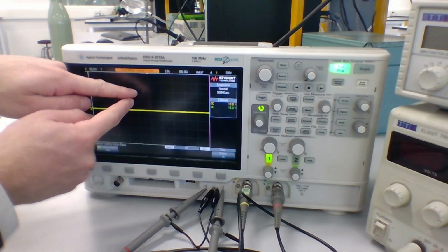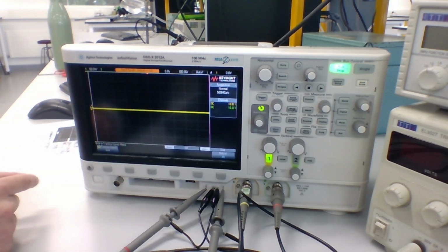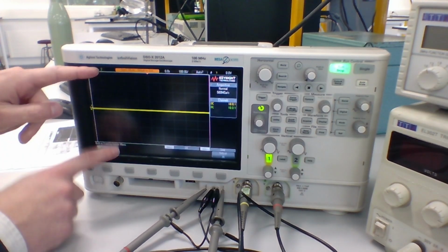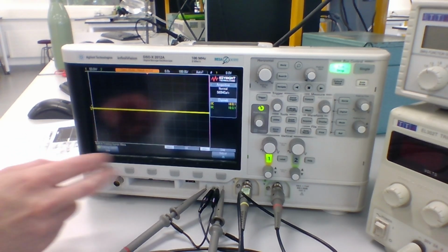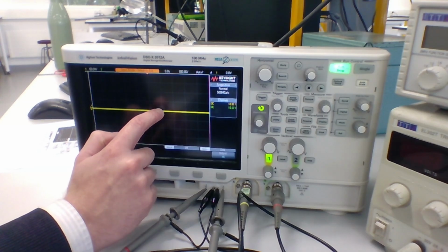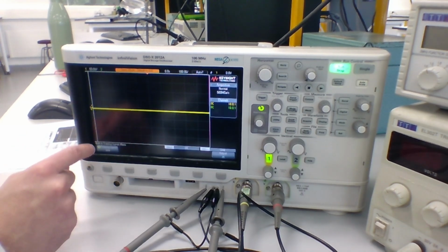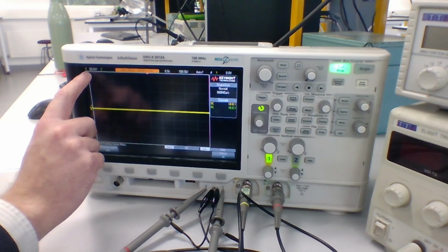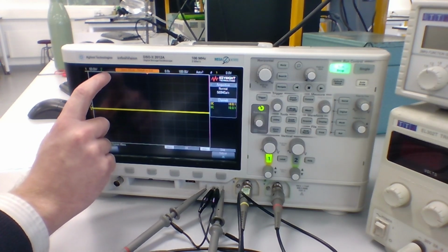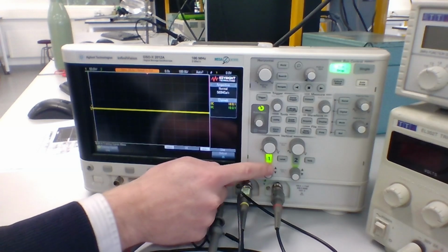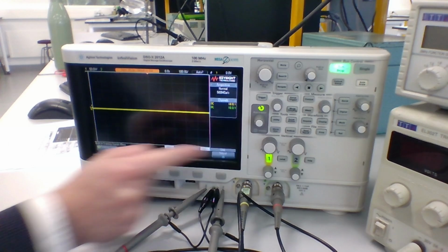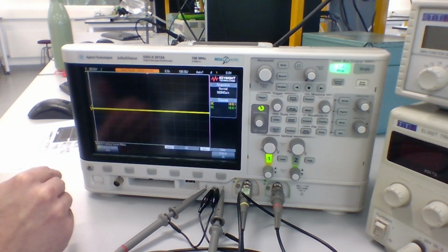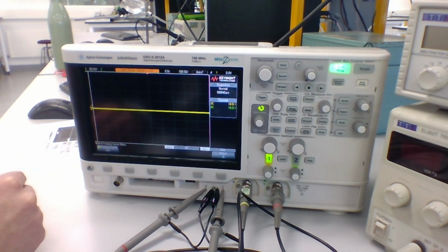We have our vertical scale and our horizontal scale. The first thing we're going to do is change the vertical scale on the screen. That is how large this is. We are looking at what is displayed on channel 1, that's in yellow. You can see it also says 1 on the left hand side here with a number next to it, and 2 has no number there. And channel 1 is on because the channel 1 key is lit up, channel 2 is not lit up, so it's off. So we know we're looking at channel 1.